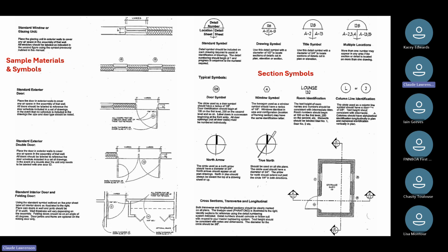And we can see here in the lower right, a little storage shed. And we see these examples of the section cuts through this particular storage shed. What we're looking at is a plan view with a door, a couple of windows, and we can see the outer materials indicate that it's brick. And inside we see a wood stud, wood frame wall with batt insulation. So again, we get to know a little bit about the language of architecture and architectural drawings. In other words, we need to know and understand how to not just look at the drawings, but how to read the drawings, getting to know them a little bit better.